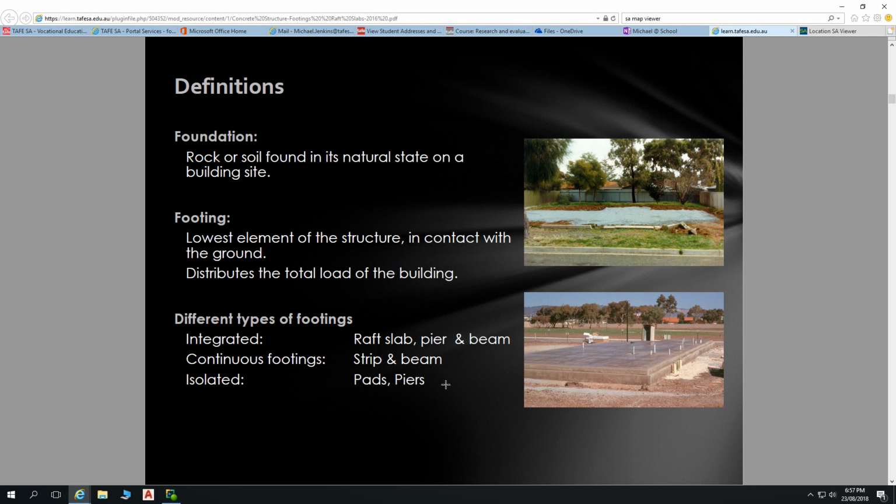That's going to happen through masonry anchors, and it depends on the kilonewtons of restraint that those masonry anchors are designed for as to how many masonry anchors we need in our bottom plate. So that's going to happen in a way that we have our footings here, and then our bottom plate on top of our concrete raft slab, and then we'll have a masonry anchor down into that concrete slab, locking our bottom plate in there.